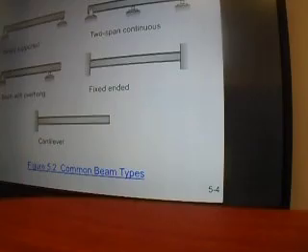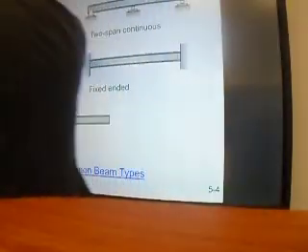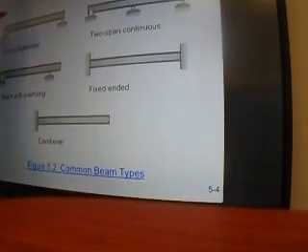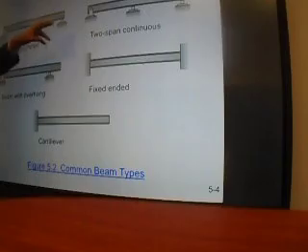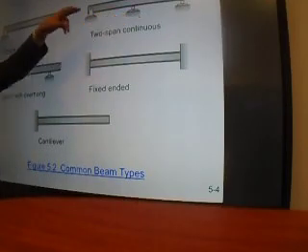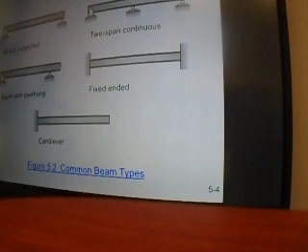So, this is what we call a simply supported beam. Okay, because it's supported only on two supports and it's only one bay. However, this is what we call two spans. Two spans. It's continuous from one side. Here, we could have multiple spans, 3 spans, 4 spans, whatever the number of spans. This is fixed-ended. This is having an overhanging cantilever part. This is a cantilever on its own. And each one of these, you can imagine, will have its own shape of deflection.